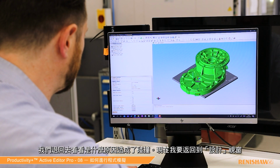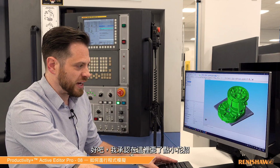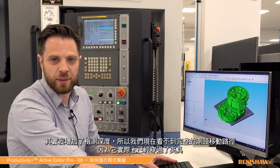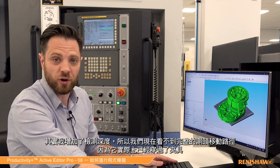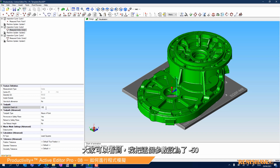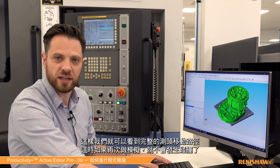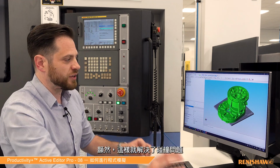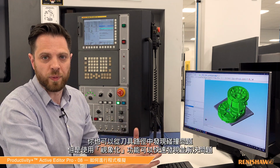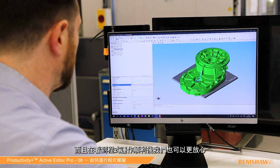So I'm going to go back to my design view. Now, I will admit, I've kind of tricked you a little bit here where I've actually increased the inspection depth to a point that that toolpath now can no longer be visible. So it's now gone through the fixture. So as you can see here, I've got that set to -50. I'm going to change that back to a -5. And what you'll see is that toolpath now is visible. So there's a good chance if we run this again, that collision won't occur. So that's obviously picked that up. You could notice it with the toolpath, but by visualizing it, it's just a quick way and a bit of peace of mind to see that everything's going to be okay.